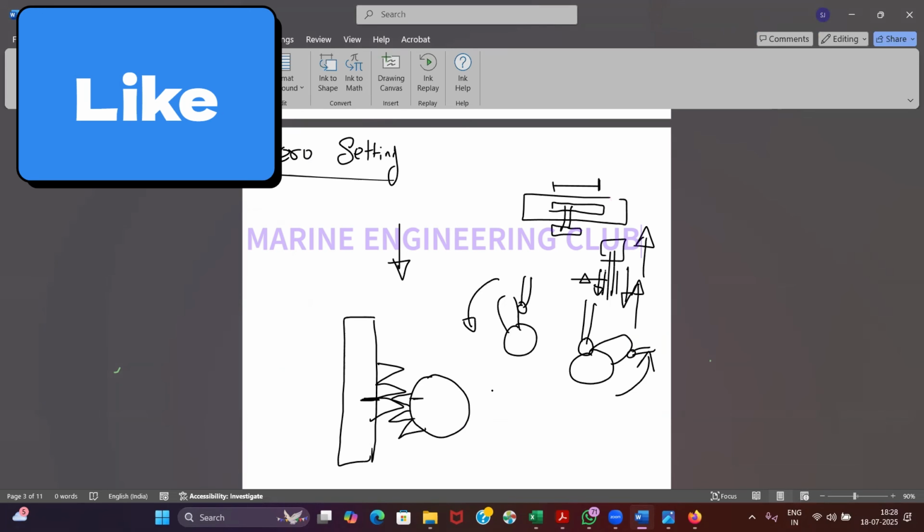So this marking should match and your plunger foot marking should match, है ना? All these three markings, when they are matching during the boxing up time, that means zero setting of fuel pump is done. Is it clear? Yes, sir. What is this zero setting?